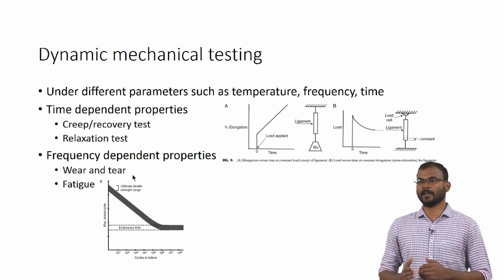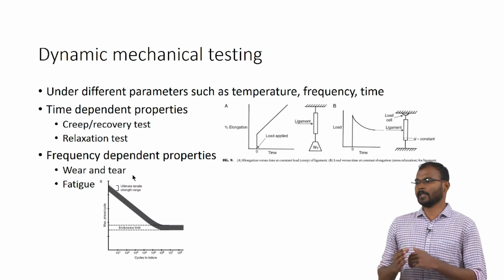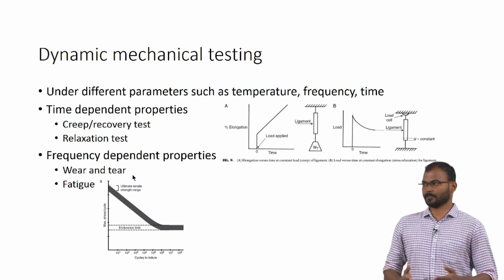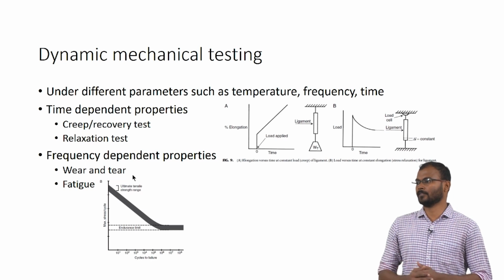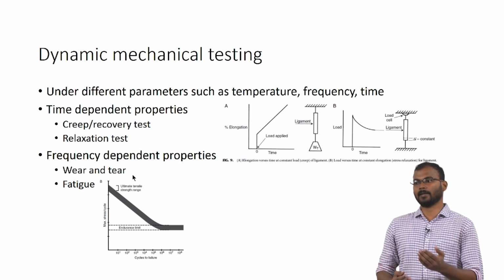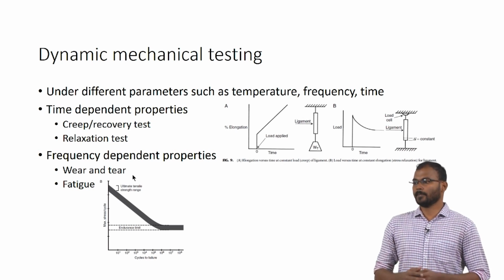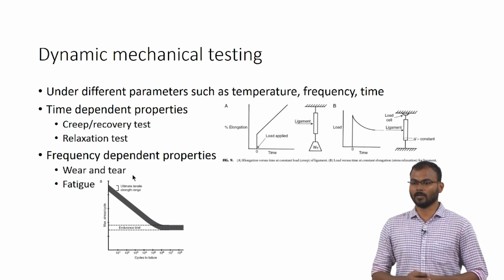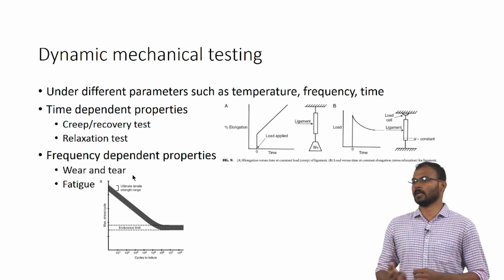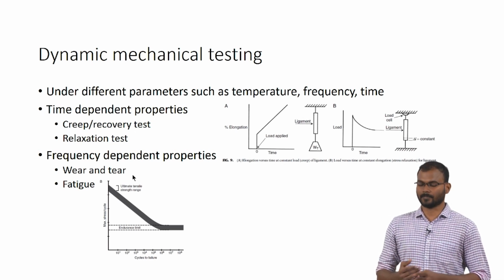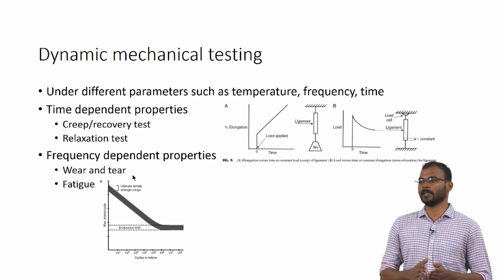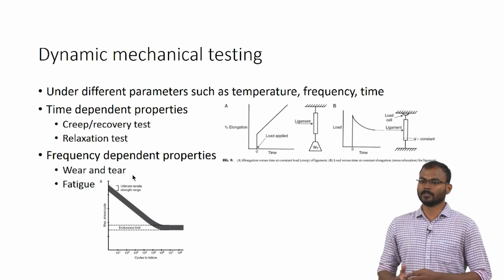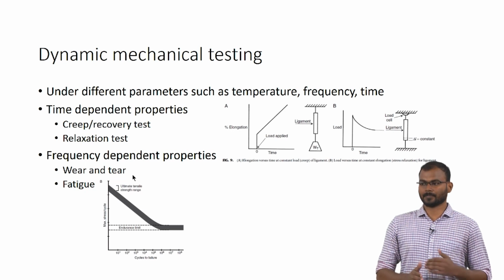Stress shielding effect is an effect where if a material can have a load of around 500 Newton, and we make that material into a 1000 Newton material, it can have that much capacity. What happens is it takes all the load by itself, and it will not pass it on to the nearby bones. So the bones surrounding that material will lose their integrity and become weaker compared to normal bones. The material is shielding the stress from the nearby natural materials, thereby reducing their integrity. That is one of the major problems in orthopedic implants.